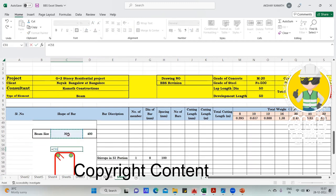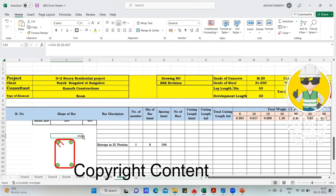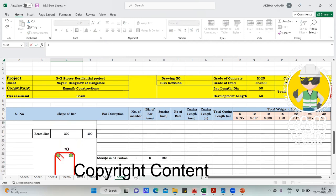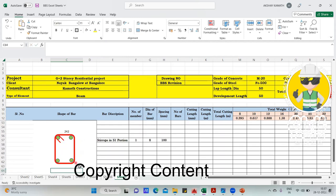So it will be 300 minus, it's a beam, no? So 25 left side minus right side minus 8 mm bar. Okay, your answer is ready, 242. It will go to the side, click on that, make it at the center. Same thing it will be here, plus, and you interlink with this. Done. Again, it will go to the corner, bring at center and finish. Okay, good. So if it's not exactly at the center, just drag it like this and then adjust this one.